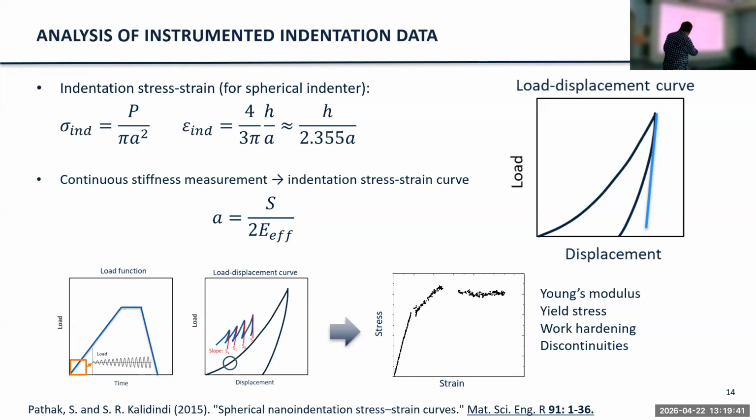So you have a little indentation stress strain curve each time. And from the unloading curve each time, the stress goes up and down and up and down. Well, you can look at the displacement and load. Are they in sync? If you do polymers, there can be a lag between them and you get a phase shift. But in metals, at least in this case, at room temperature, low temperature plasticity where there's no creep, you can determine from these unloading curves and the mechanics, if you know the Young's modulus,